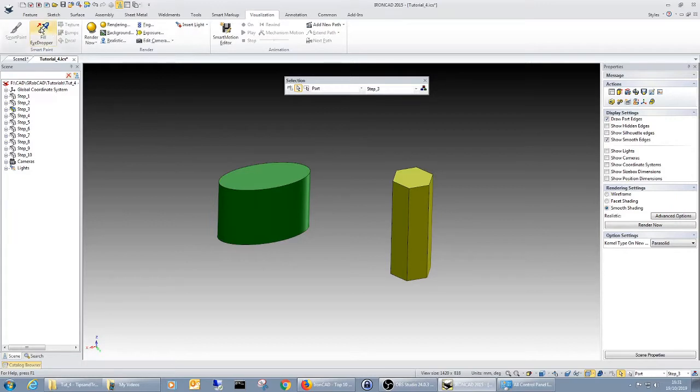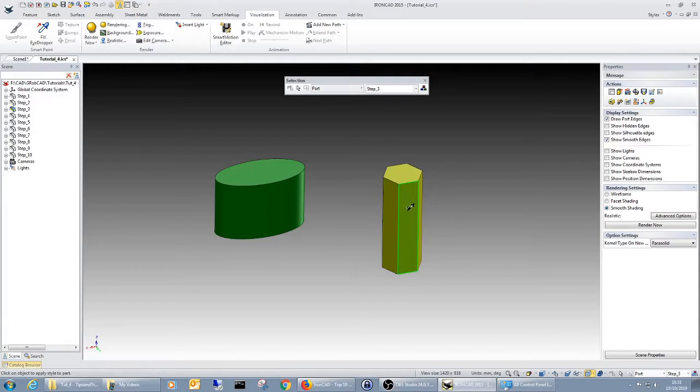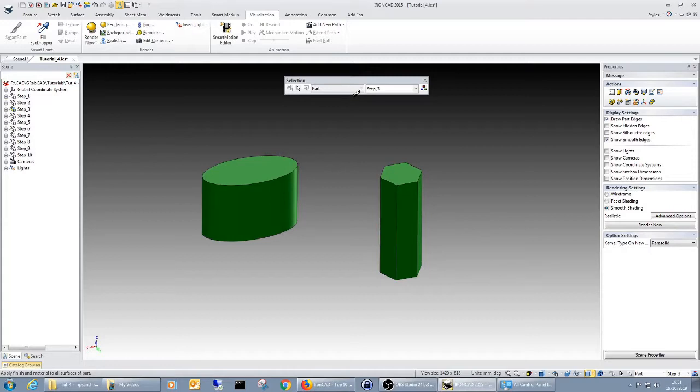So we go up and select the fill eyedropper tool there. Changes the icon, so let's suck up the properties there, and you move over to the yellow part, and instead of left clicking you right click here, and it gives you a nice little menu there. So you can just go for surfaces, parts or groups here, but you can also go for the material of the part. Let's select that one. So it also changes the colour obviously.